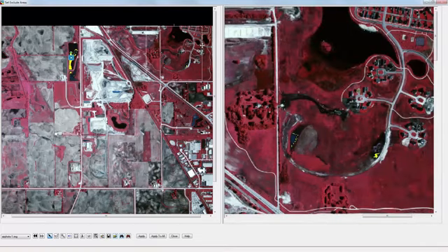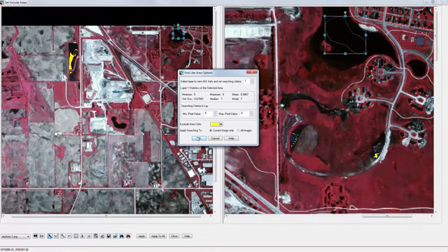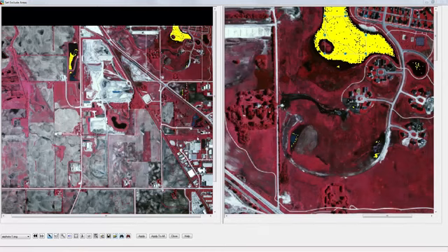There are still some dark and light pixels that should be excluded from the color balancing algorithms. Digitize a polygon in a dark area and click Find Like Areas again. Notice that the yellow areas highlighting the excluded pixels will compound every consecutive time, adding to the original excluded pixels, but not replacing them. When satisfied with the excluded pixels from AirPhoto 1, click Apply to All.